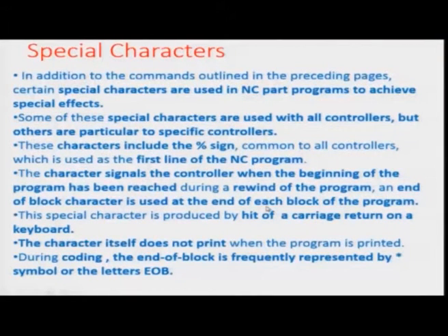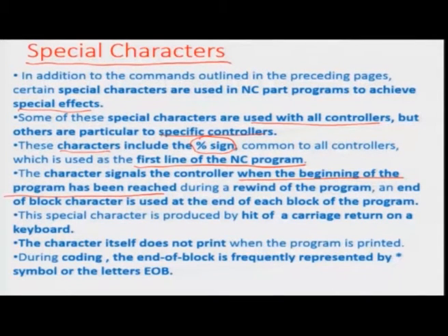So, last but not the least, there are special characters which are also a part of the code. These are in addition to the commands outlined, and special characters normally have special effects. Some of these characters, for example, are used with all controllers, but others can be with specific controllers. There is a character called percentage sign, which would be common to all the controllers, and it is generally used as the first line of the NC program to suggest that it is a program start. Okay. So, the character signals the controller whenever the beginning of the program has been reached during even a rewind process of the program,